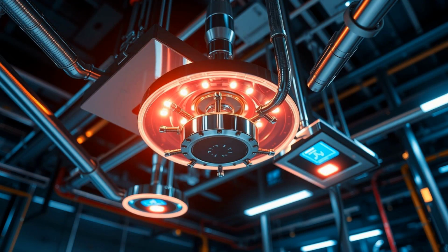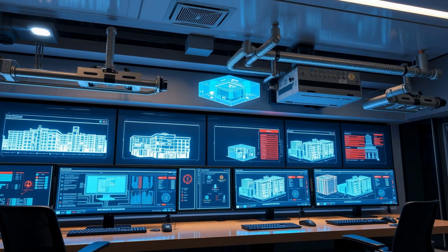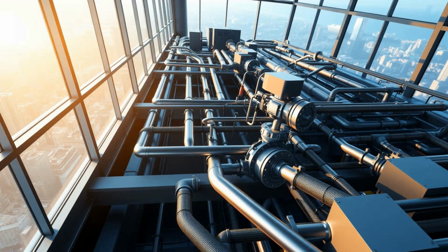Technological advances are also revolutionizing fire sprinkler systems. Smart sprinklers equipped with IoT sensors can detect changes in temperature trends, flow rates, or valve status and send real-time data to cloud-based platforms. Building management systems, BMS, can now integrate fire sprinklers with HVAC and security systems for coordinated emergency responses. In high-rise buildings, multi-zone systems with pressure-reducing valves are used to ensure balanced discharge across multiple floors.